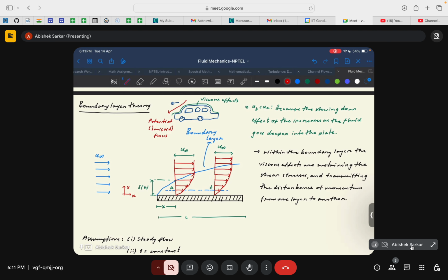So if you remember, when we first discussed boundary layer in these problem solving sessions, I told you that the formation of the boundary layer and the fact that we are able to demarcate between the viscous region and the inviscid region does not mean that the viscosity is zero in the inviscid region. The viscosity is very much present, because there cannot be any fluid which has a viscosity of zero. It's not possible. But the only thing is that in that region the velocity gradients are so small that they are not able to manifest the shear stresses from the surface of the object.